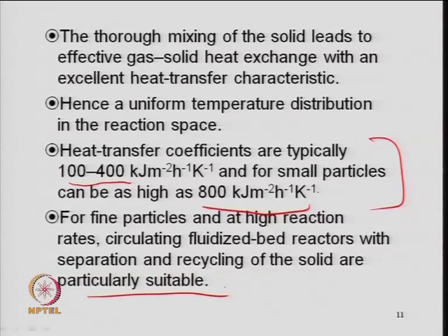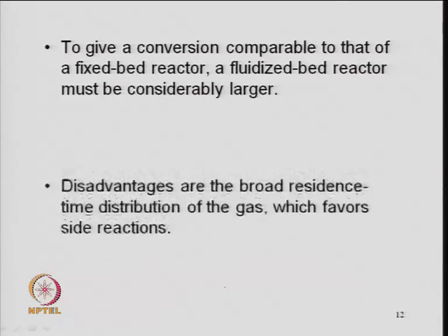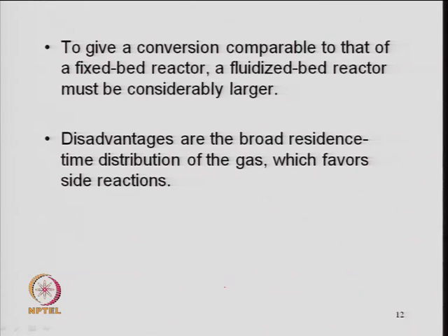It is not difficult to separate the solid particles or unreacted particles. So, you separate the particle and send it back into the system, right. So, heat control and everything is possible here. So, if you need to give a conversion comparable to that of a fixed bed reactor, as I said, the fluidized bed reactor behaves like a CSTR.